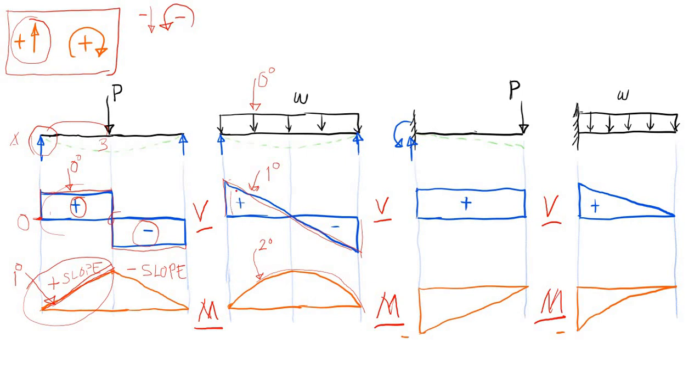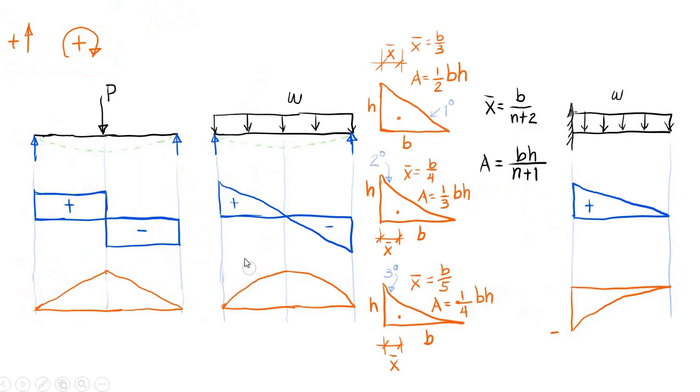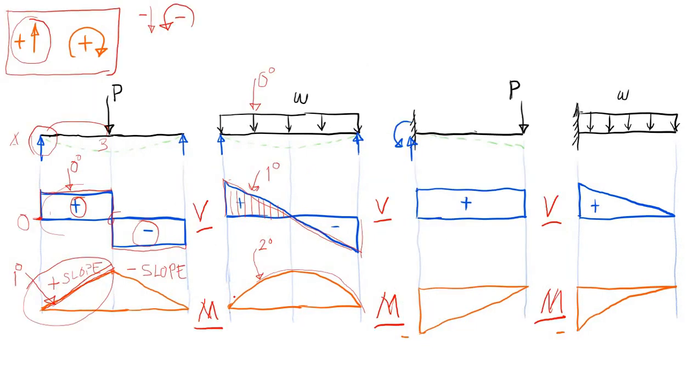Now notice, guys, that if we are going to consider the intensity of our shear, take note that the intensity of our shear is decreasing. And since this is positive, our moment should be having slope upward. So this must have a positive slope.